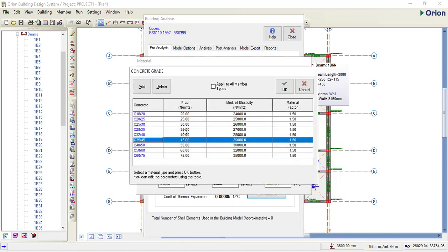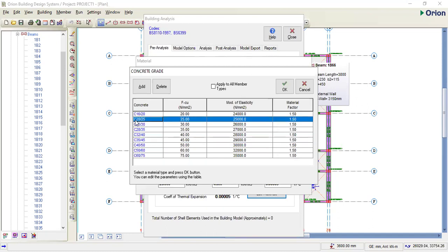In this case, we are using, in fact, after the project, what do we call the carcass? All the contractors brought out the concrete cube tests that we have, and we confirmed that some of the grades are even more than 25 strength of concrete, 28, 30, 32 we have.